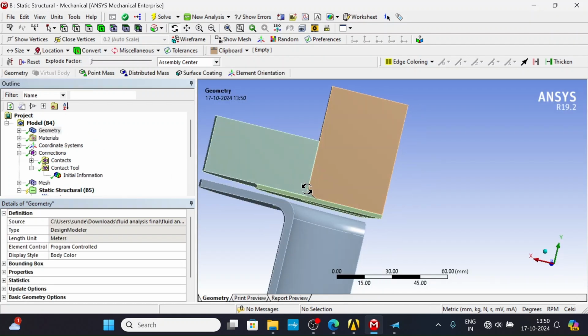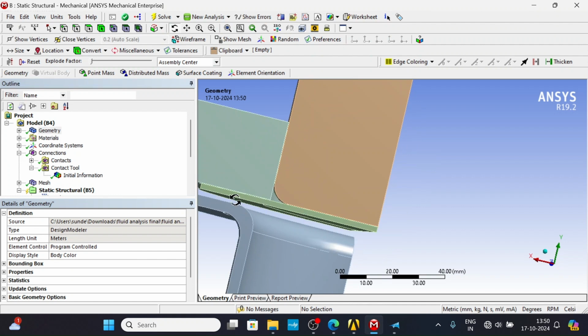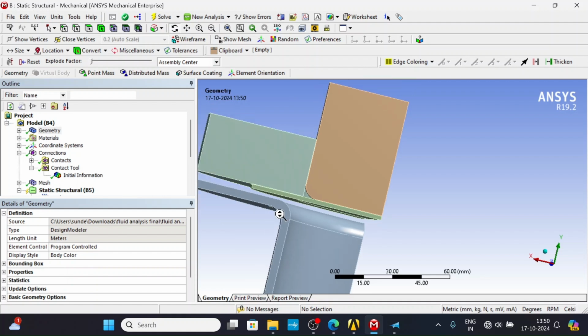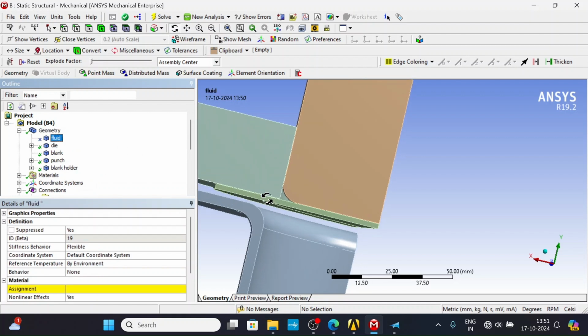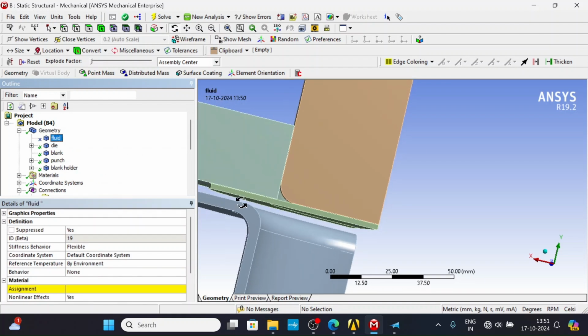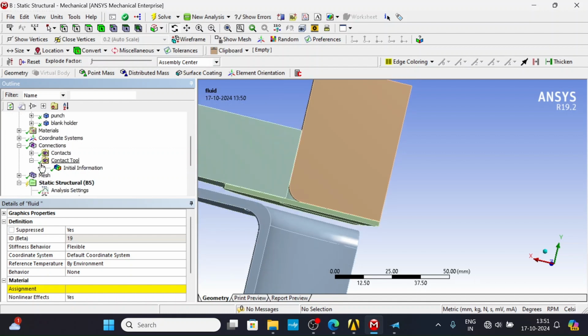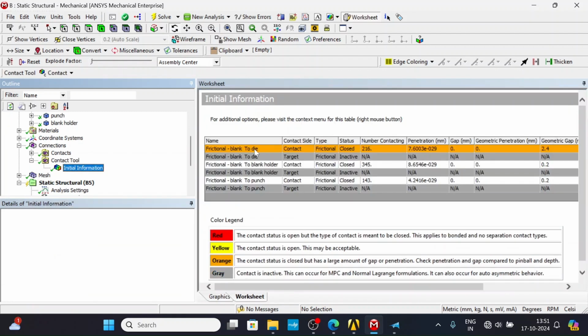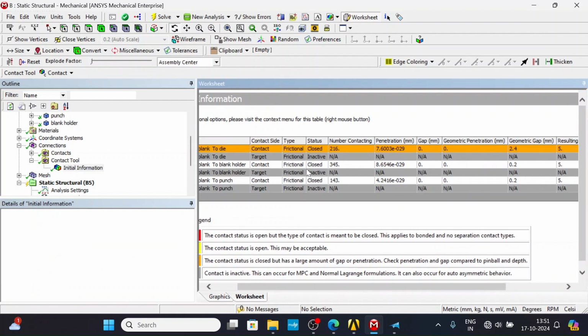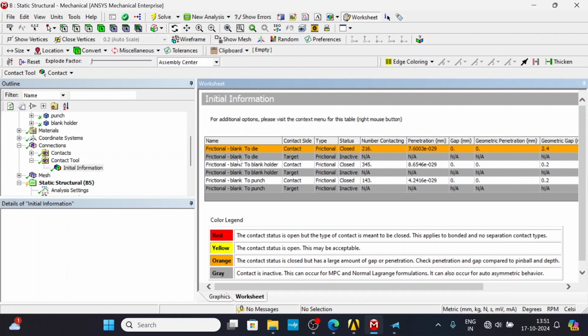We have this huge gap where the 2 mm outlet of the fluid medium was supposed to be, but we suppressed it. Since we removed the fluid part from our simulation, there is a large gap. That is what it is talking about. The remaining two contacts are good; only one contact has the issue with the large gap.